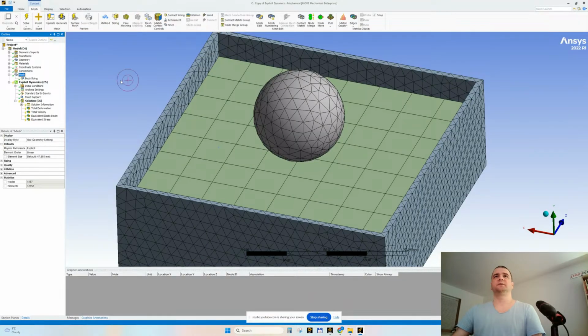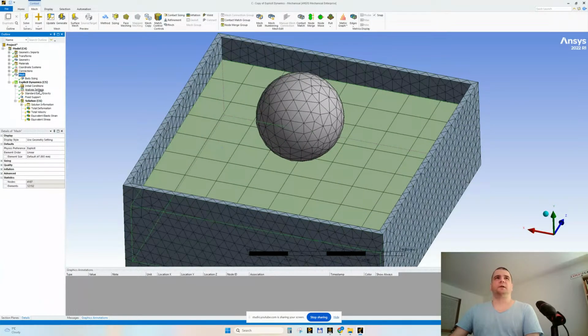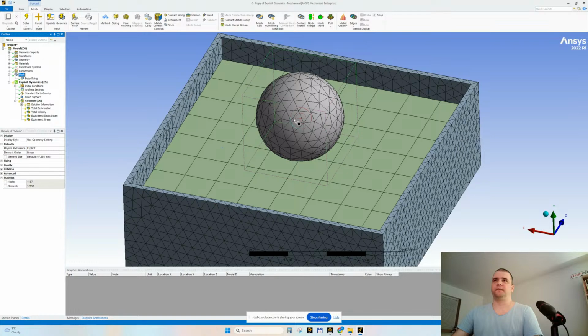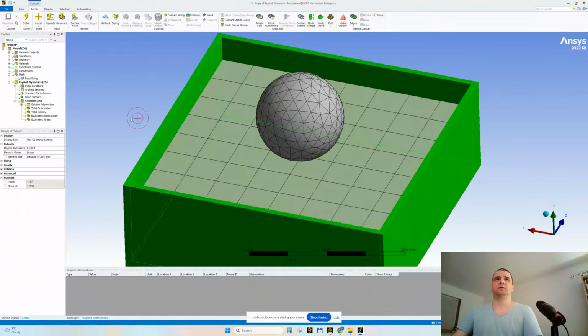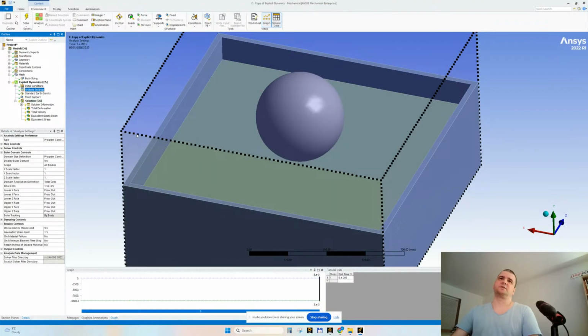So I said that I don't care about the mesh of the water. Sincerely, I don't care about the mesh of the tank too much. But yeah, let's not overkill it. What we need to correlate is the mesh sizing of the impactor and also the surrounding tank with this mesh sizing or density, yes? And they are kind of the same.